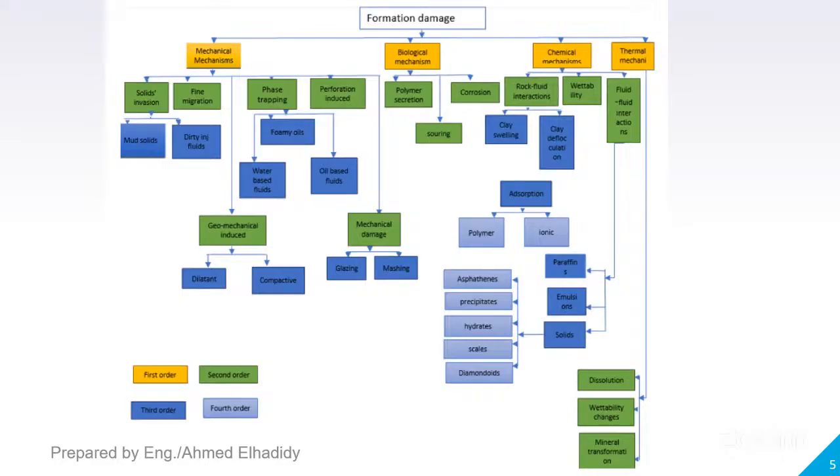Also, if you have clay particles, once the flow starts to move, it starts to break down these particles, and they also move with the flow, plug the pore throats, decrease your porosity, and then decrease your productivity.